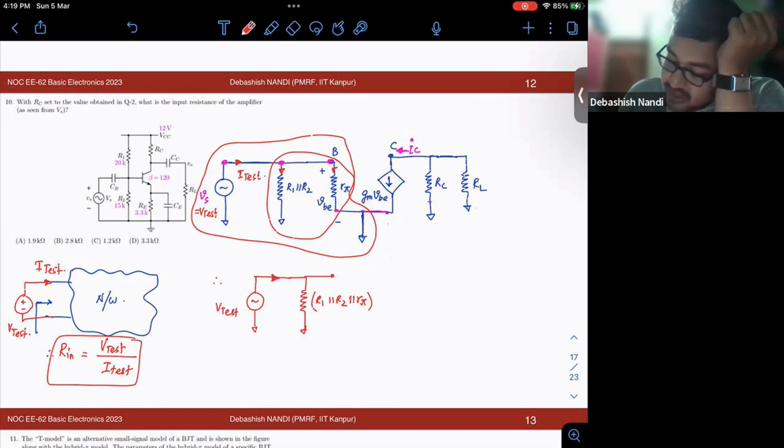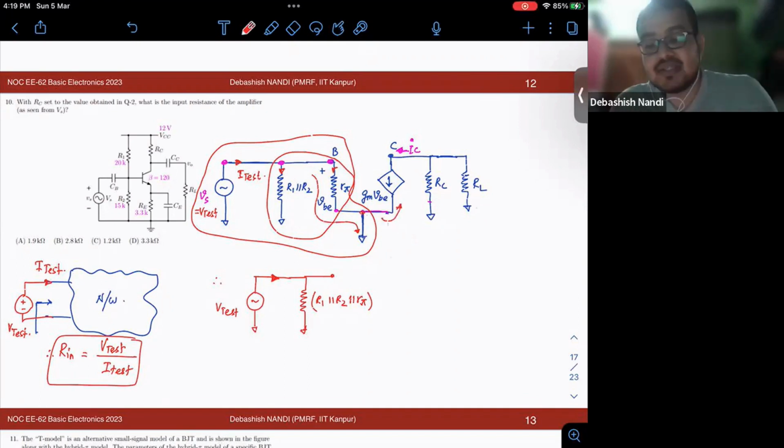This current is flowing through this, right? Why is it not flowing through the here? Here it will see certain impedance, right? It has two paths. One is directly grounded, another path it is seeing some non-zero impedance. The entire current will flow through the short circuited path, right?